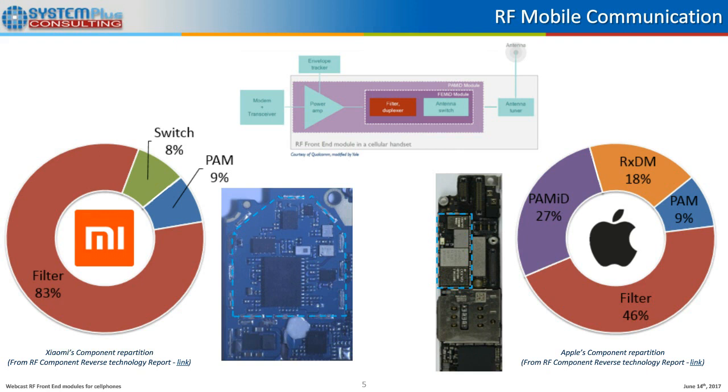So to begin with, I will talk about the entire RF system in mobile phone. The RF module system that allows communication in a well-known smartphone is actually composed of several blocks. The system has a power amplifier, filter to provide the best SNR on the selected frequency band, antenna switch to provide communication on several frequency bands, and antenna tuning to match the impedance of the antenna according to the frequency. And depending on the constructor's choice, all blocks of the diagram can be integrated in one module or in discrete mode.